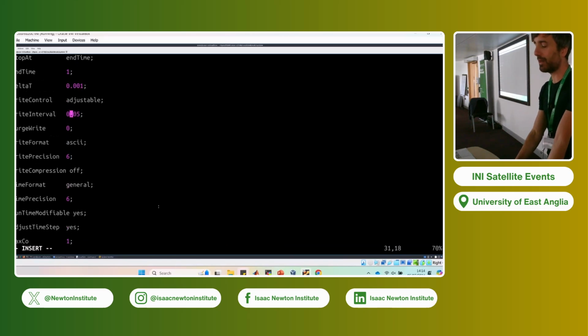But still, even with a variable Courant number and variable time step, OpenFOAM will try to save the data every 0.05. So it will adjust the time step at the right moment in which it needs to save data.